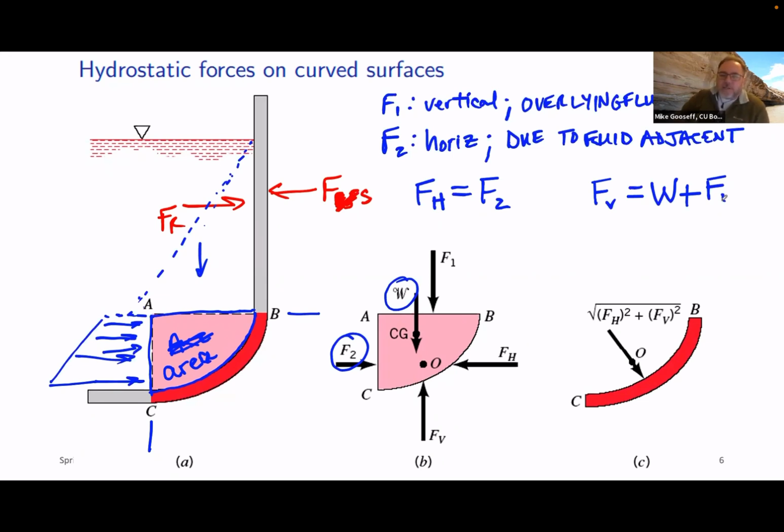So you can imagine that we're not taking the square root of F1 squared plus W squared plus F2 squared. We are working through the sums to figure out the X component of FR and the Y component of FR to keep this in place. Then we take the square root of the sum of the squares of each of those components.